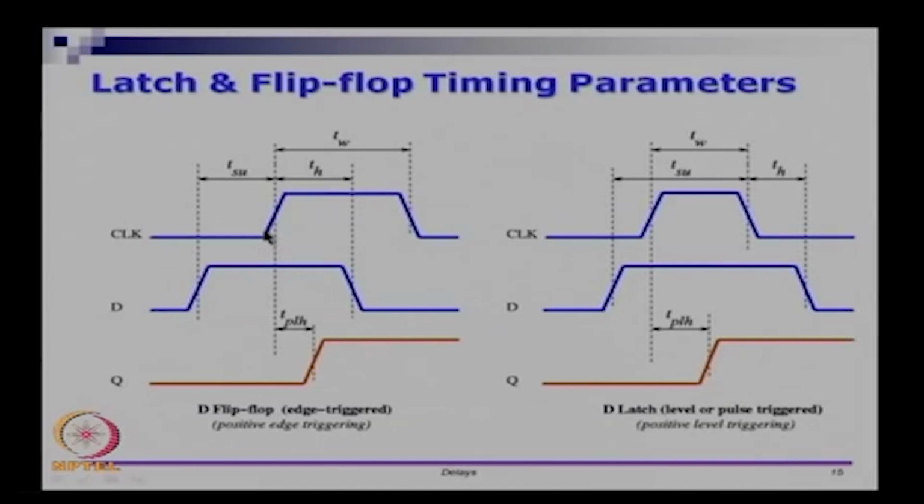So there is a window of time in which the flip flop is actually letting you sample, right. This window of time is just the rising edge of the clock. You are going to sample the input only at the rising edge of the clock, and no matter what happens to the inputs at any other point of time, it does not matter to a flip flop. So if you want the input to be correctly sampled,